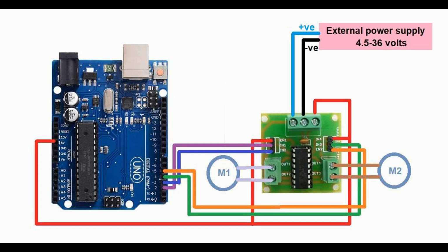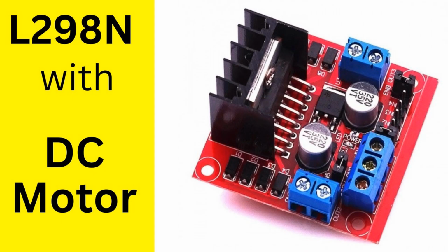4. BLDC motor drivers with field-oriented control, FOC. Function: FOC is a more advanced control technique used in BLDC motor drivers that allows precise control over the motor's speed, torque, and position. FOC drives the motor based on the vector control method, aligning the current vector with the rotor magnetic field for optimal efficiency.